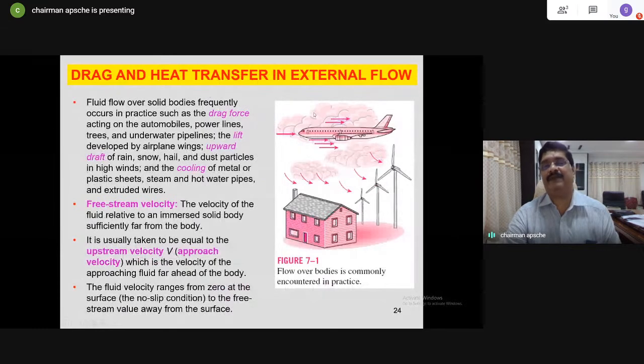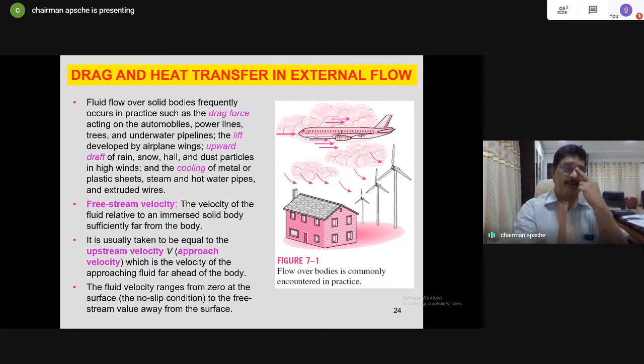The drag and lift, those who study aerodynamic actions and aeroplane movement. Lift force is vertical upward movement, which happens because of the pressure difference between the bottom and top of the moving body. And drag force is the opposing force. If it wants to move forward, the air resistance or fluid resistance stops it from moving. Normally we talk about drag, and aeroplane flying is explained very well with these two forces, lift and drag.